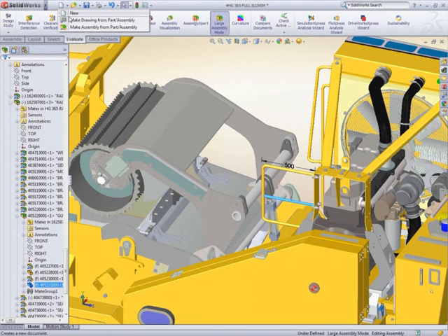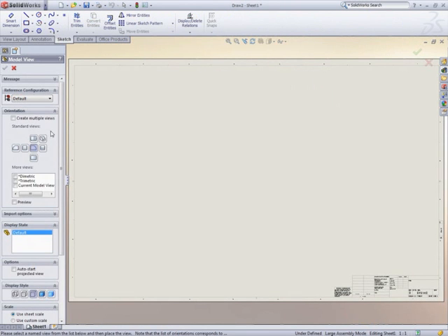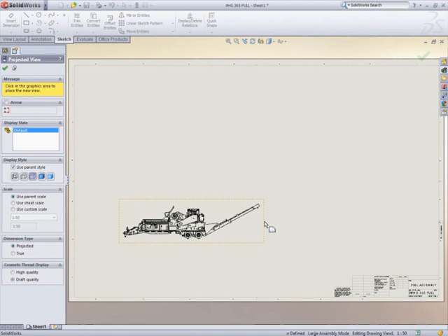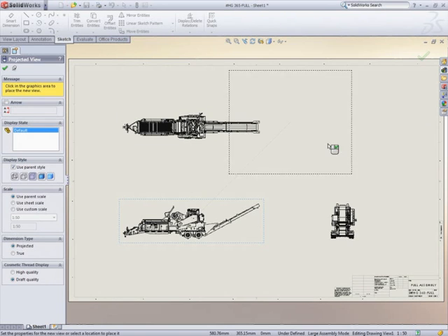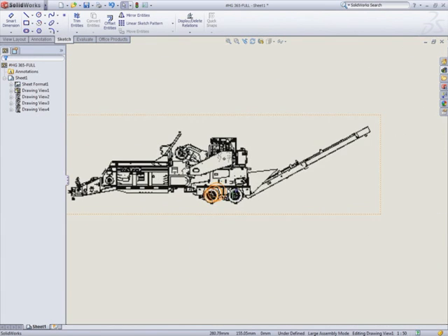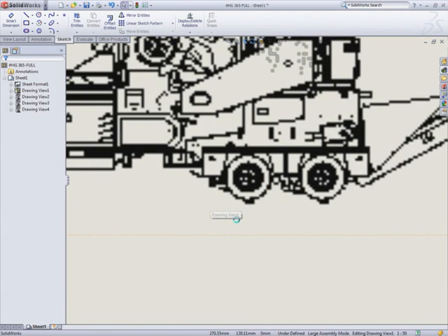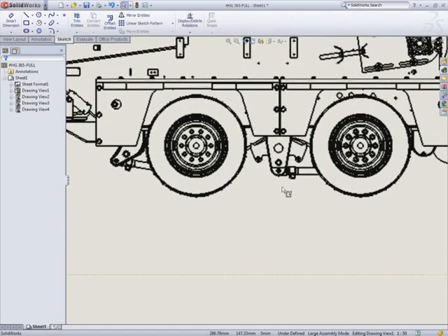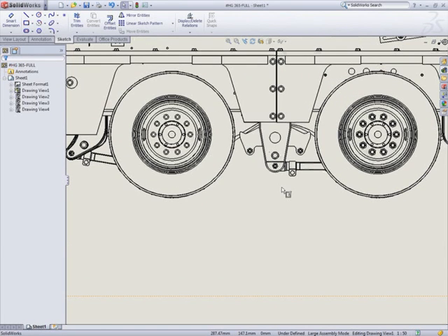But what about drawings? Well, we have the geometry of all the parts already, so making the drawing is easy. However, SolidWorks does use some clever tricks, invisible to the user, to speed things up. We can see how quick it is to lay down 4 views of this 6,500 component assembly, and moving around the drawing is also quick, as SolidWorks uses image refinement technology to reduce the amount of data on screen at any one time.